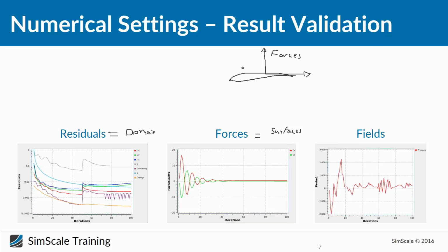Basically, what I wanted to point out when I talked about the residual convergence criteria is that you can define it based on what you think makes sense. For example, for external aerodynamic cases, a good rule is to have a convergence below 1e-5 for all field values. But for other applications, like transient simulations, you have other values. In the end, you should define for yourself what convergence you want to have and follow this approach. Okay, but let's continue.